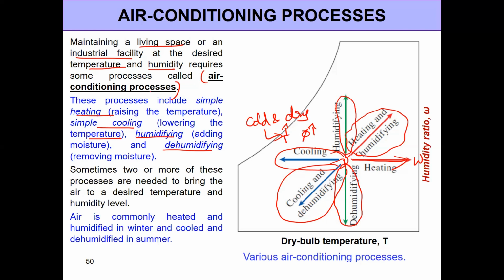On the other hand, in summer, the air around us is hot and humid. It's relatively humid even in most places. So in this sort of condition, you would want to reduce the temperature for sure, but at the same time, you've got to bring down the relative humidity. We want to keep relative humidity at about 50%, plus or minus. 50% is a good value to keep it, but anywhere in the 30 to 50% range works very well for us.